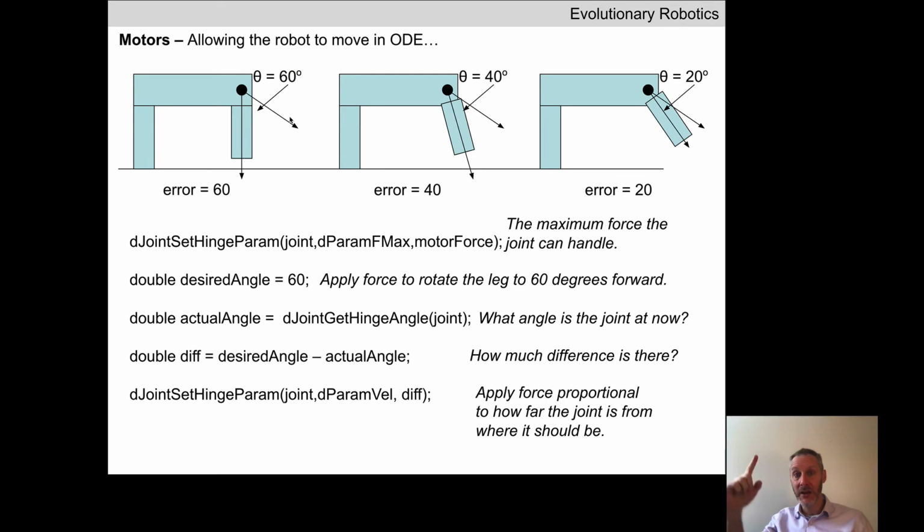Usually the desired angle is also changing. So if we have a quadrupedal robot that we're looking at from the side, and we want that robot to trot, that means that all the legs should be moving together and it should be hopping from point to point. So the desired angles are going to change sinusoidally. What happens in that case?